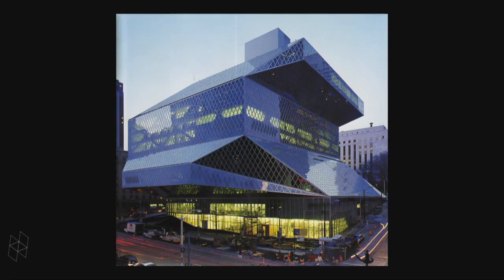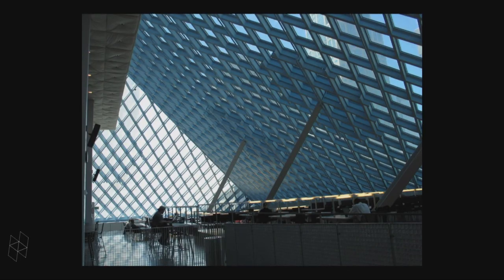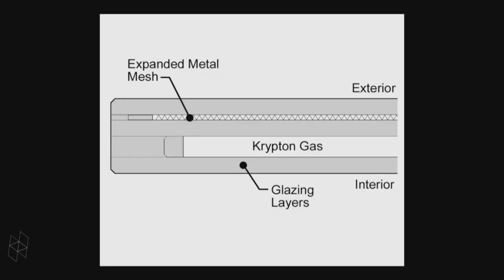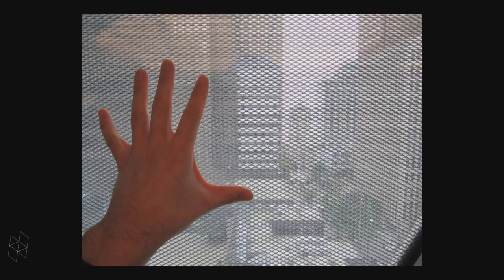Other strategies: for an all-glass building like the Seattle Public Library, you should know that it's gaining lots of heat, even in Seattle. So the architects understood the structure as a kind of shading device, but also embedded within the glass is a micro mesh that does regulate heat gain on the faces that actually see the sun. So there's a permanent, adapted way to regulate heat on this building. All the faces that see the sun have the micro mesh to control that heat gain question.